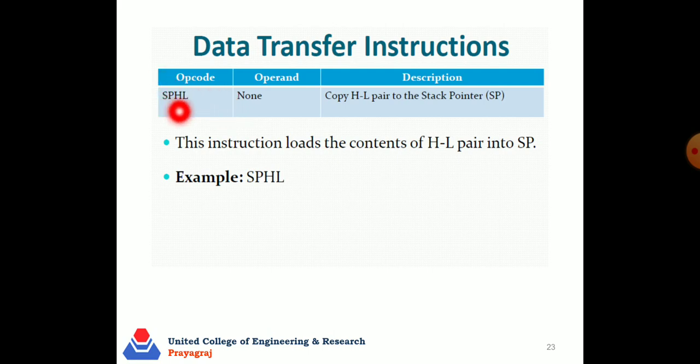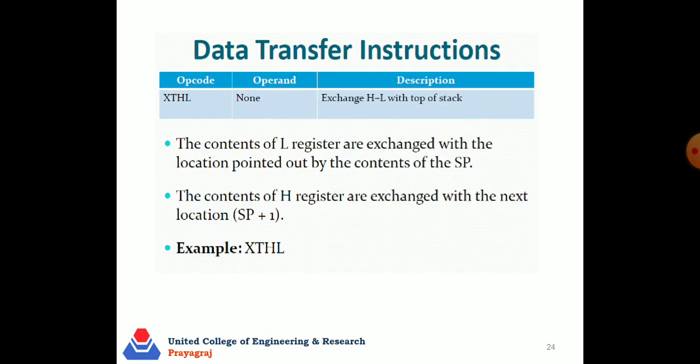And the meaning of SPHL: SP is the stack pointer, HL is the register pair HL. So, the meaning of SPHL is copy HL pair to the stack pointer, which means this instruction loads the content of the HL pair into the stack pointer. So, the value of the stack pointer depends upon the HL pair. It is a very simple instruction. Next instruction is